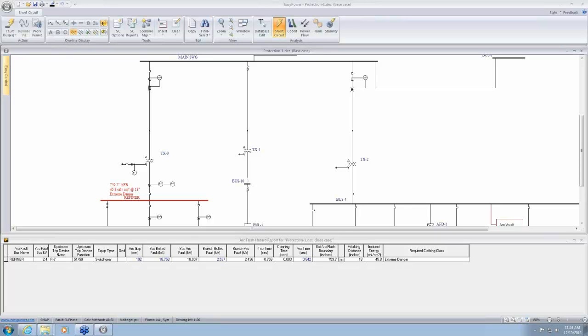Now, if you have any circuit breakers where the nameplate has been scraped off, or you cannot read it, you don't know what it is, and you think you might be able to get by using generic, you're most welcome to use generic as a standard estimate for that particular circuit breaker for which you have no other information.